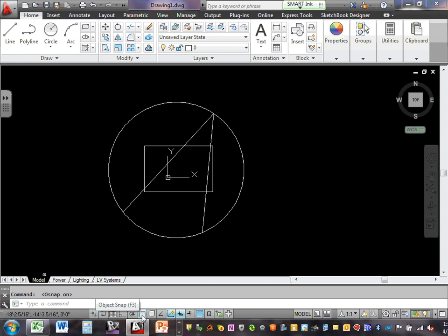Let me go set your object snap, the most common ones that I like and you need. Shall we? Object snap, guys, when you draw a line and you want to start, here's a circle and you draw a line. Now you're holding the line. It tells you, do you want to snap it to the center of the circle? Do you want to snap it to the perimeter of the circle? Do you snap it to the edge of the line, the middle of the line? So there's a lot of places when it's snap, it means they lock it with that particular location. So great when we're laying out our receptacles, guys, when you drop receptacles, say snap into the wall. It sits right into the wall. It's not over, it's not behind the wall. See how powerful the snap is?